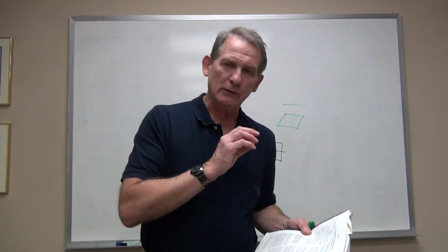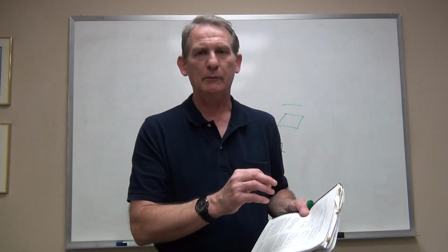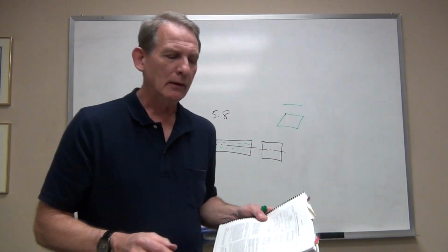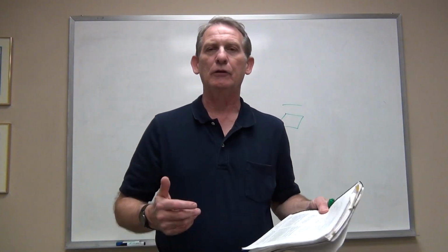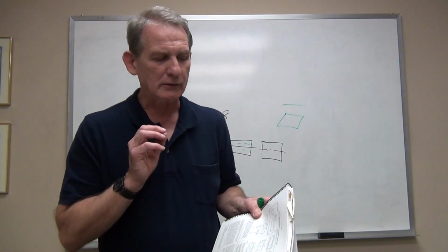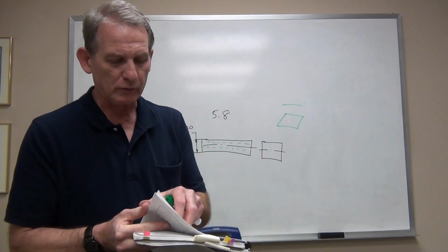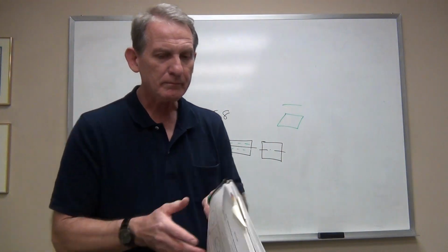You might imagine it's a kind of a painstaking thing to establish the derived median element and measure how much curvature it has. You can actually design fixturing that if the part fits in it, it is good. You haven't measured anything, you have checked it functionally, and this is the basis for the functional gauging. But again, don't worry about that. You won't be held responsible for any of that.